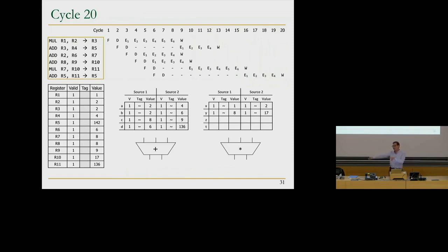But you cannot take an instruction that's after the add and rename it, because that will break all of the linking that we do in terms of renaming. Renaming is all in sequential order, so that you can link the instructions. You cannot do out-of-order renaming. I mean, you could, but it complicates the system a lot, and people don't do it.